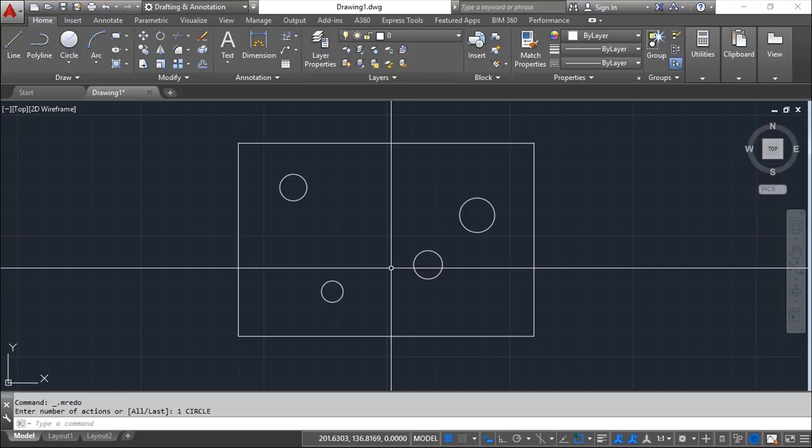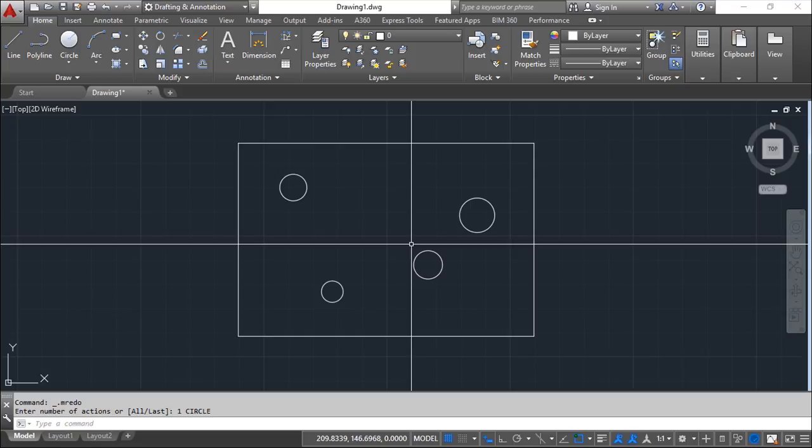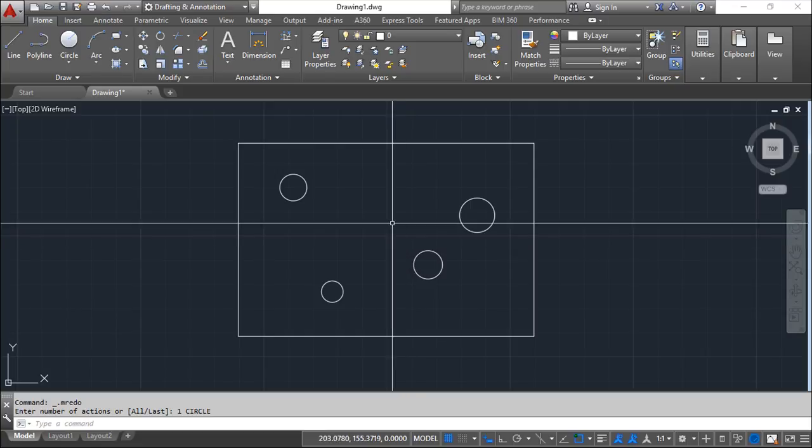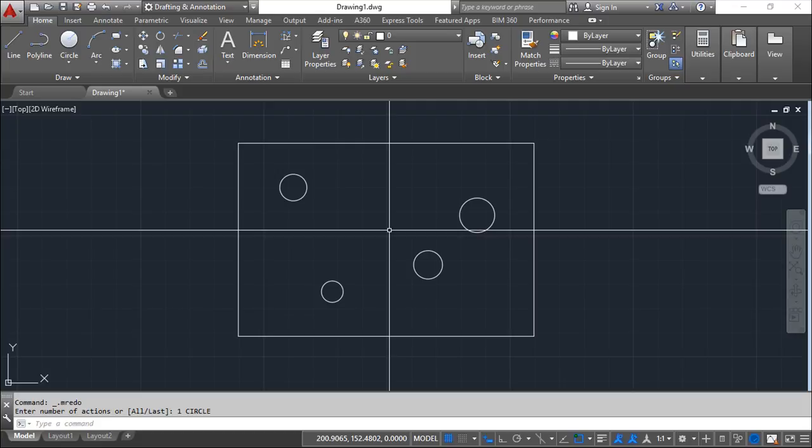Basically, one example where this kind of dimensioning is very used are injection molds, because besides all these things I've mentioned, when we are putting dimensions in drawings that have a lot of entities, it will be almost impossible to understand what the dimensions were for. So this is another way to dimension things in reference to something and with fewer entities, because it will only put one line per dimension, as you are going to see.